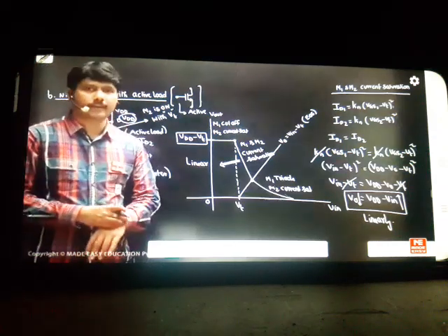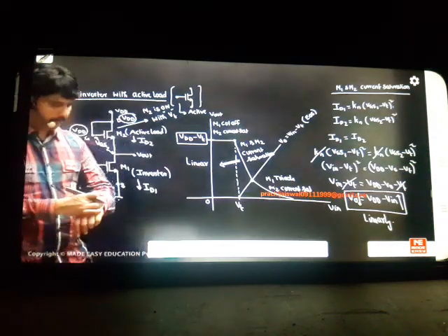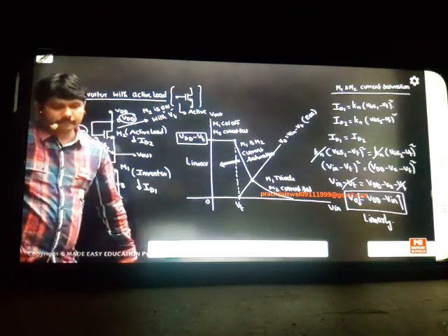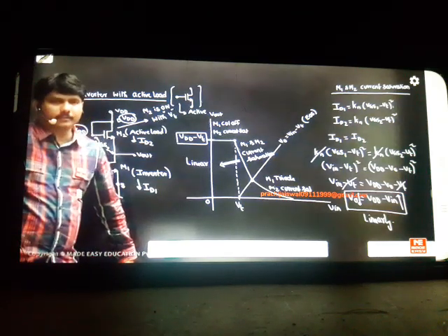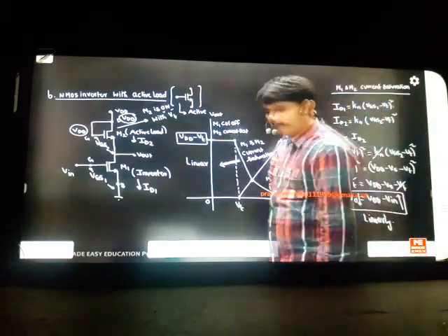The second transistor is not off here, we have biased it already. It will have some minimum threshold voltage inside the device. So we have to subtract the threshold to tell the highest output. So this is one of the drawbacks of this concept. In the previous topic we got the highest voltage but we are not getting it now. Suppose VDD is at 10 volts, threshold is 1, we will get 9 volts in this concept because of the active load.